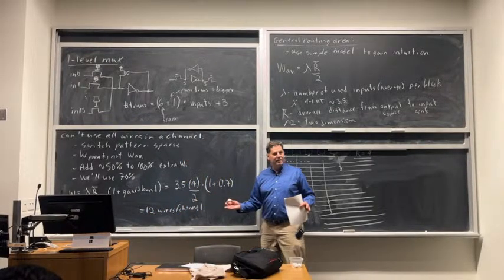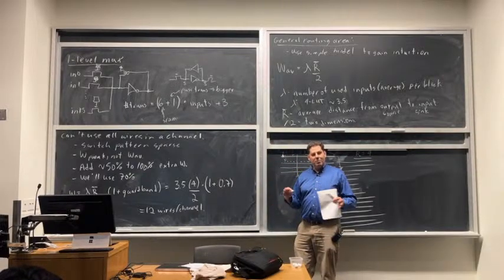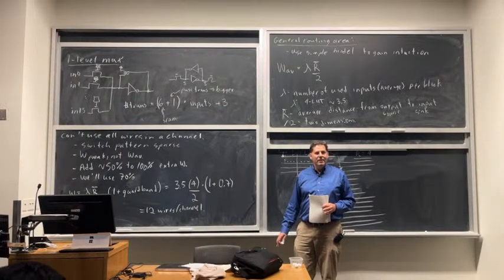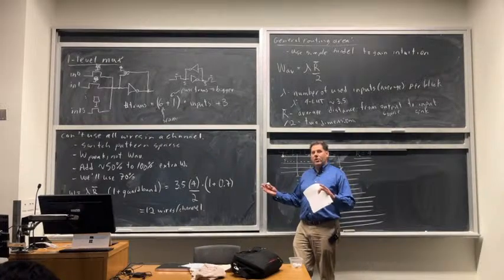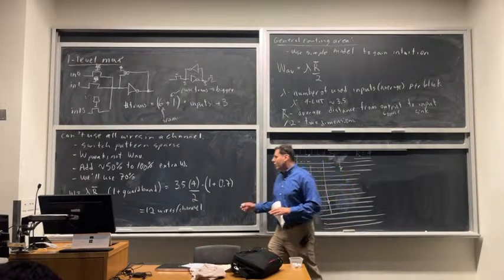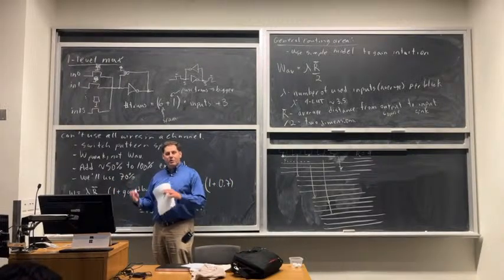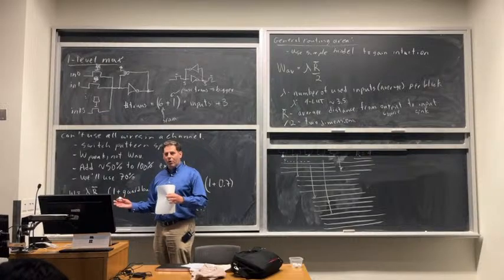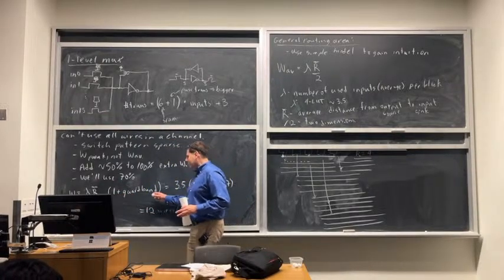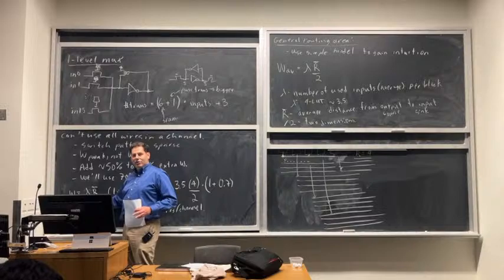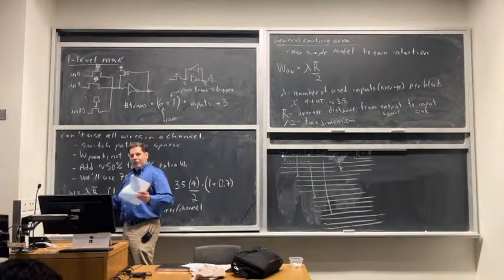Does that make sense? Arria 10 also has a lot of longer wires for speed. Longer wires do cause more blocking. You tend to waste some of your wiring when you have longer wires. You don't always use the whole thing. So the main difference is that lambda is hugely different for an architecture like Versal or Arria 10. It's much bigger, and that's why ours is a much narrower channel. But it's also why these equations are quite useful, because even though this is hugely different from that commercial architecture, I know it still makes sense. And people do make FPGAs with really small logic blocks, and when they do that, they should make their routing channels a lot smaller.